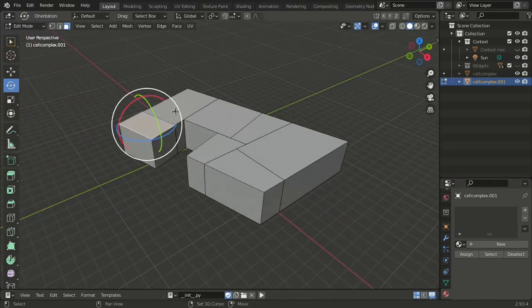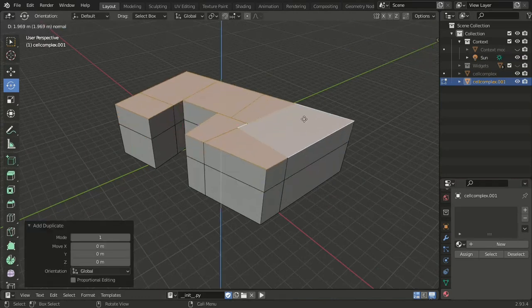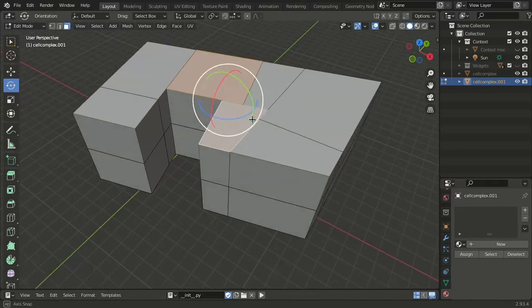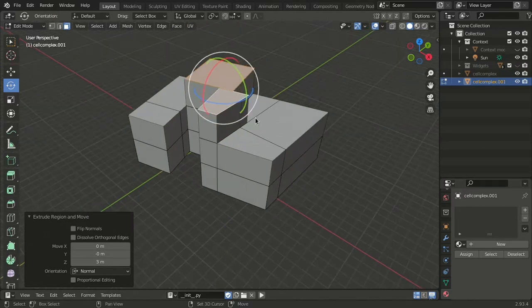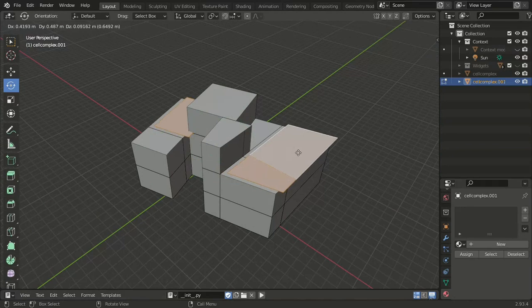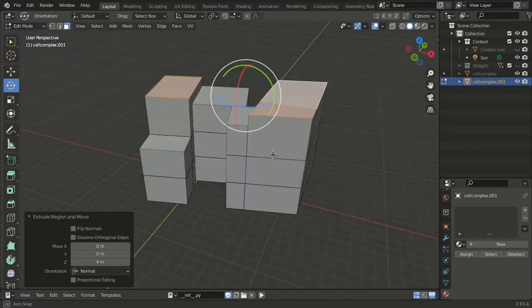Topologic discards any geometry that doesn't define an enclosed space, so I can model overlapping faces without worrying about aligning vertices or other fiddly details. The Homemaker add-on analyzes this cell complex and dismembers it into a collection of paths or traces that form the basis for generating IFC elements such as walls, roofs, footings, slabs, windows, etc.